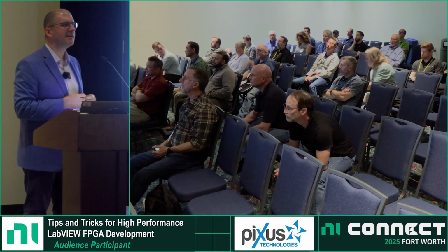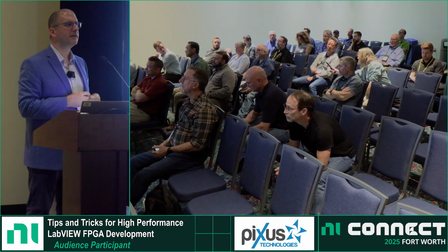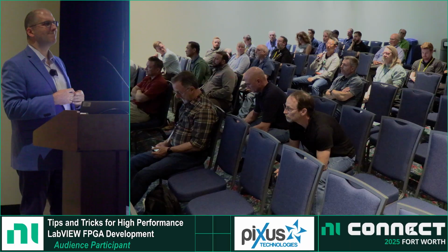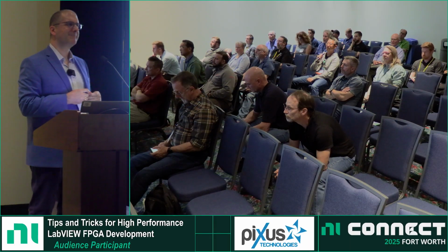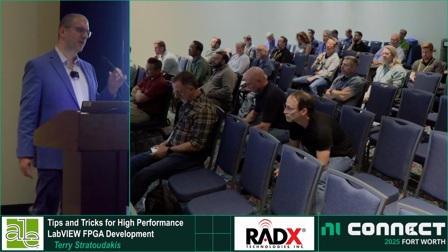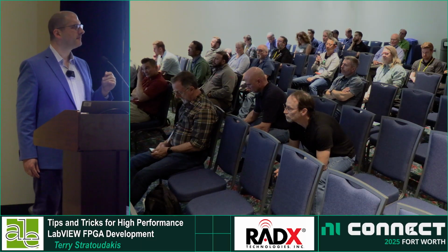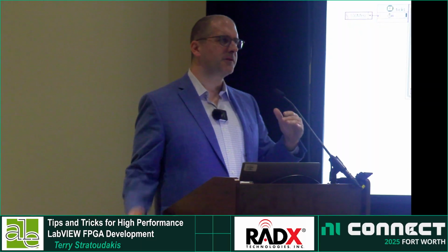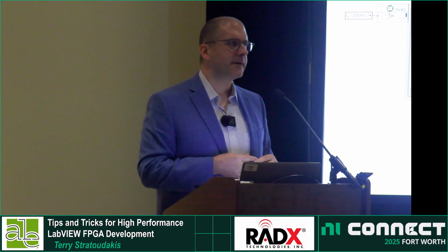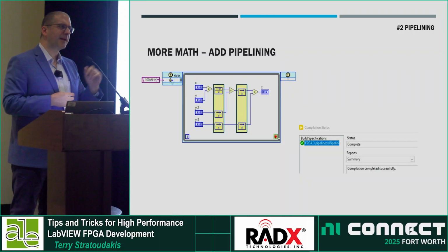Is there a way to tell if the timing is going to fail before you try to compile it? There isn't. The definitive answer is when you compile. Unfortunately, it takes some experience. Sometimes you may get a sense of what may fit. Pipelining can get you pretty far.